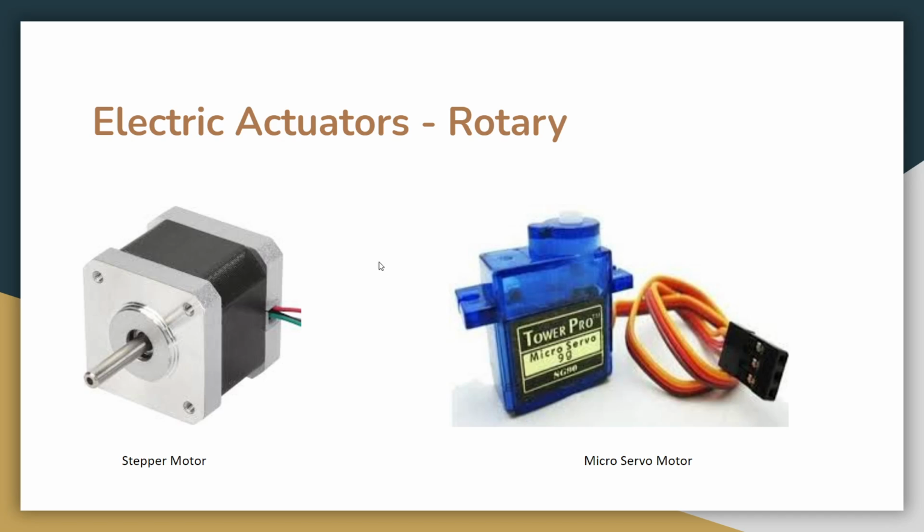So basically, the stepper motors and servo motors, essentially you're going to be giving them PWM signals, and depending upon the PWM signal which you give, the rotation and the angle are going to be mapped and specified respectively.